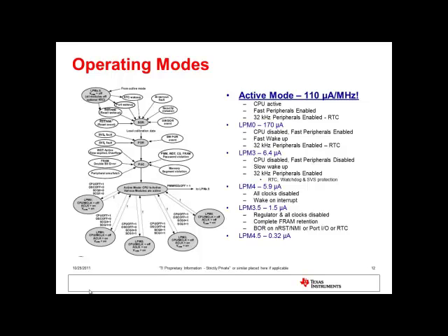LPM3.5 and LPM4.5 are more specialized modes that allow the digital core to be turned off while retaining minimum functionality, allowing the device to hibernate. This mode is also known as deep shelf mode. An example application where this mode is used is to store battery-powered products in warehouses before shipping to an end user. The products are required to consume extremely low power while maintaining, for example, the time or the ability to wake up from a switch interrupt.